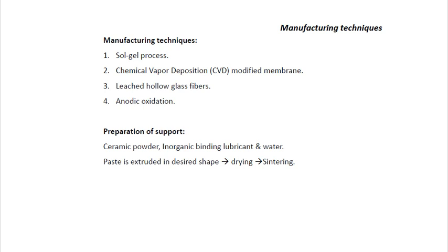In this process the first step is the creation of the support of the membrane, because generally our inorganic membranes are also asymmetric membranes. So it has a porous support as well as a non-porous or very less porous thin layer above that, which will act as the separation media, and the porous support will provide mechanical strength to the membrane. So the first step is to create the porous support.